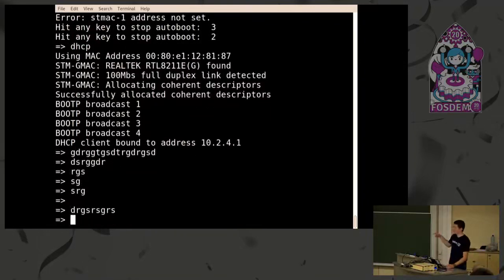This is a script that I made for FOSDEM, so if I enter one command, it won't crash. What I'm using for MetaLava is that if it's not exactly the right command, it crashes. This is just for showing you. If I want to boot, I'm just typing a boot command. Usually it's bootm with the right addresses, but just for the demo, I made it boot only.